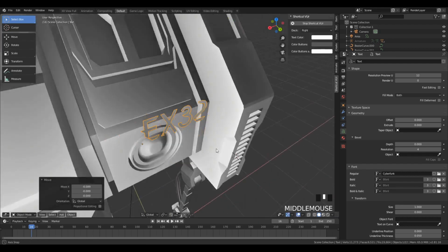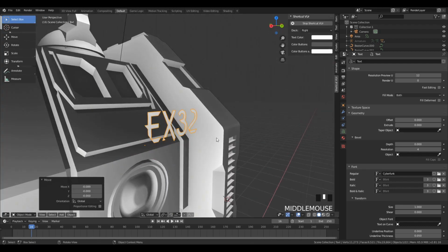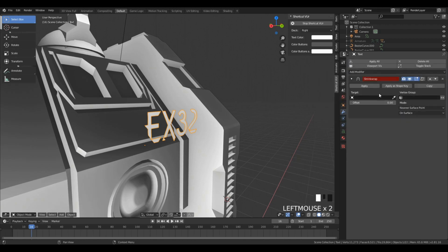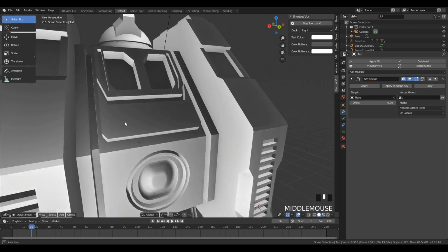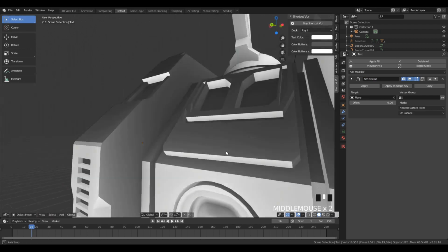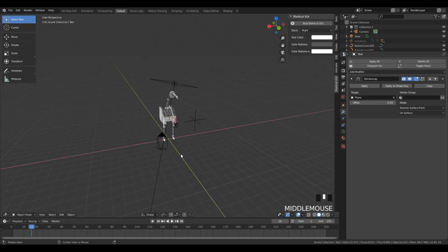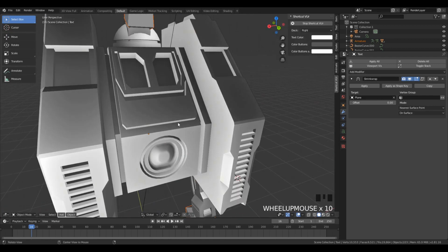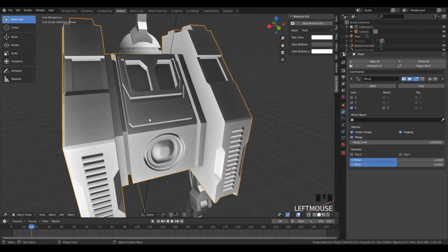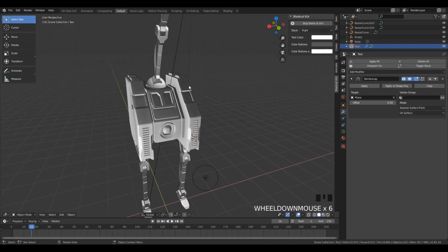Now you want to position this close to your mesh, but it doesn't exactly matter where, because we're going to use the shrink wrap modifier. We'll click shrink wrap here, and then select the object that we're going to attach it to with the eyedropper tool. Now, you'll see that it's gone. Why is that? It might have attached to something that's not actually there. Oops. Let's make sure this armature is hidden. Let's find that text.